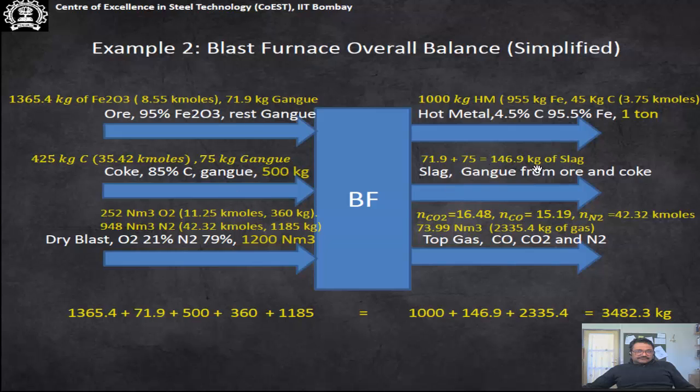Of course, as I told you, if SiO2 or MnO etc. get reduced, then that much amount of SiO2 etc. has to be taken out from the slag. So when you do the SiO2 balance or MnO balance, that needs to be taken into account. In addition to it, if there is a fluxing, which is often there, that also needs to be accounted for in the slag.